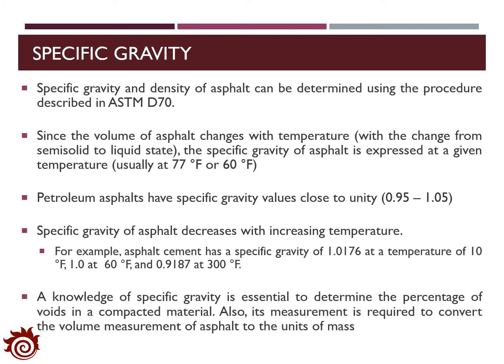Another thing we should know is that the specific gravity is very important to determine the percentage of the voids in the compacted materials, which will be very important for us to learn the Superpave. Also, we can use the specific gravity to convert the volume measurement of the asphalt to the unit of mass.